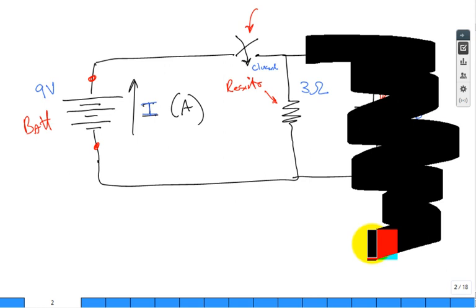No. So isn't it just Ohm's law at this point? So you have the current is equal to the voltage difference, which is the 9 volts provided by the battery, divided by the ohms, the resistor. And is a volt divided by an ohm an amp? Is it 3 amps? Let's grade it.